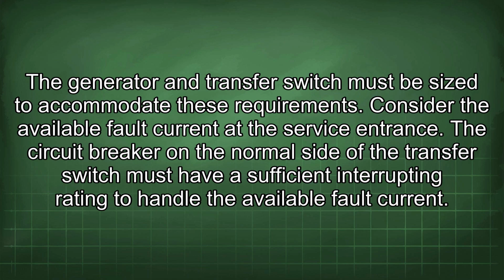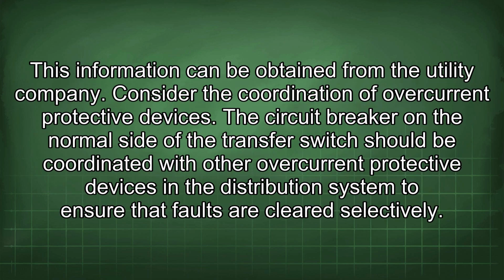Consider the available fault current at the service entrance. The circuit breaker on the normal side of the transfer switch must have a sufficient interrupting rating to handle the available fault current. This information can be obtained from the utility company.